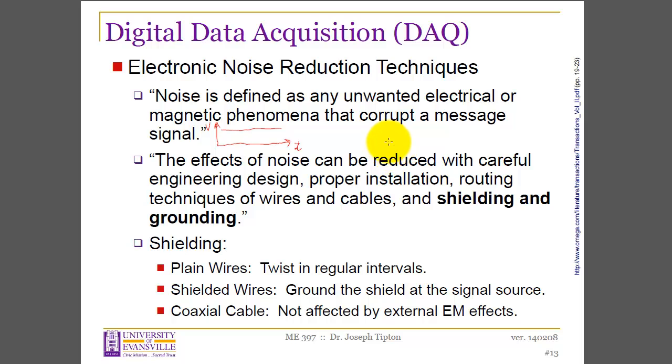Instead, we have these electromagnetic effects, essentially the connecting wires acting like antennas almost. And that results then, instead of your nominal voltage, you do have that, but you have an error on top of it. And there's the noise on top of the signal. You probably noticed that as you were testing your first LabVIEW program.